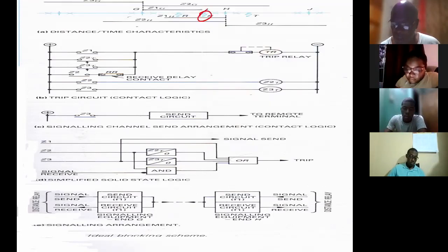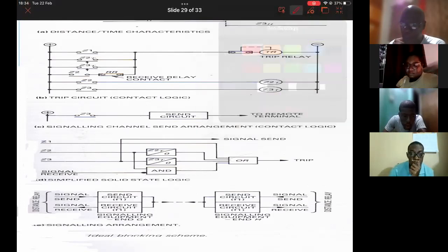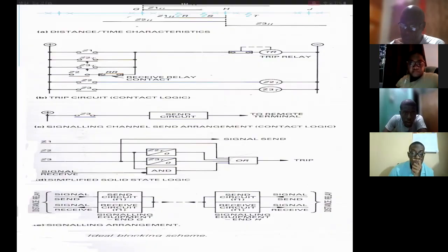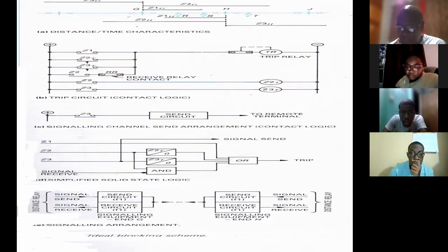Next, let's look now at fault S. Where is fault S located? Sir, it will be in zone 1 for H and zone 2 for G. Okay, so in terms of normal operation, what would we have expected? The instantaneous relay for zone H. All right, so H would be instantaneous, and it is in, as he said, zone 2 for G.